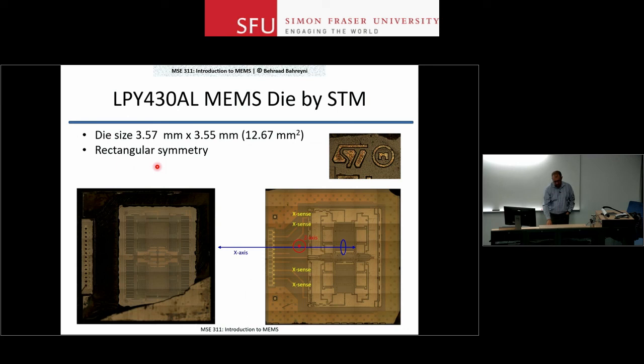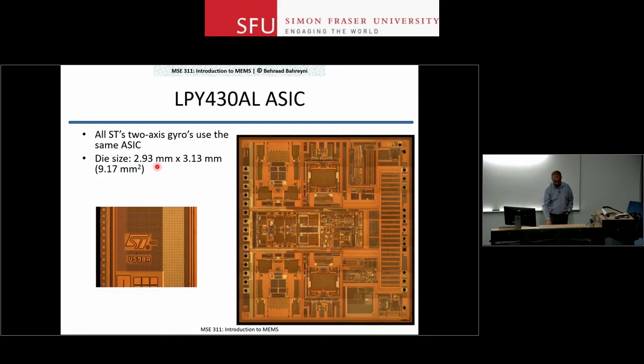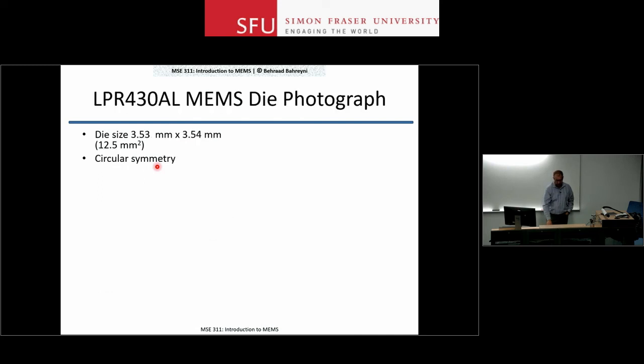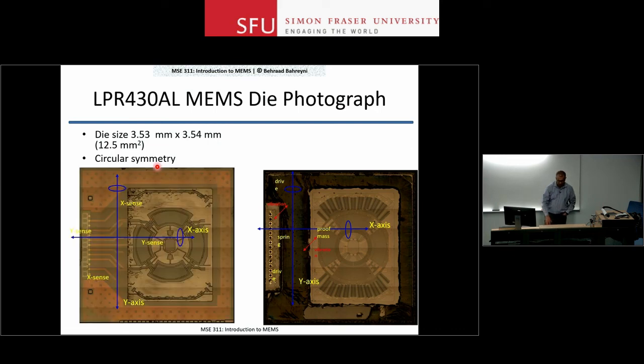And then, the structures: we usually have a two-chip solution for gyros. You make the MEMS device on one chip and the electronics on another chip. Alternatively, you can combine MEMS and electronics in one process, in one chip, but you lose a little bit of performance on both sides. Here's an example from ST Microelectronics. This is a vibrating wheel type of device, so you have the MEMS device at the top. This is the wheel that is going back and forth, and then you have a bunch of electrodes underneath to detect the wobbling of that wheel when it is subjected to angular rate.